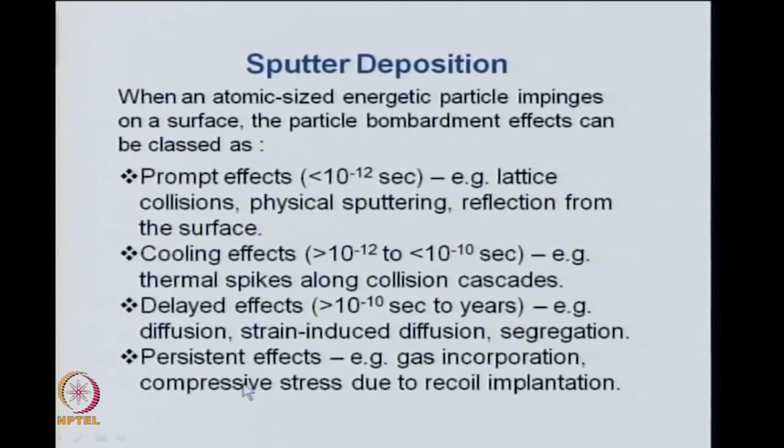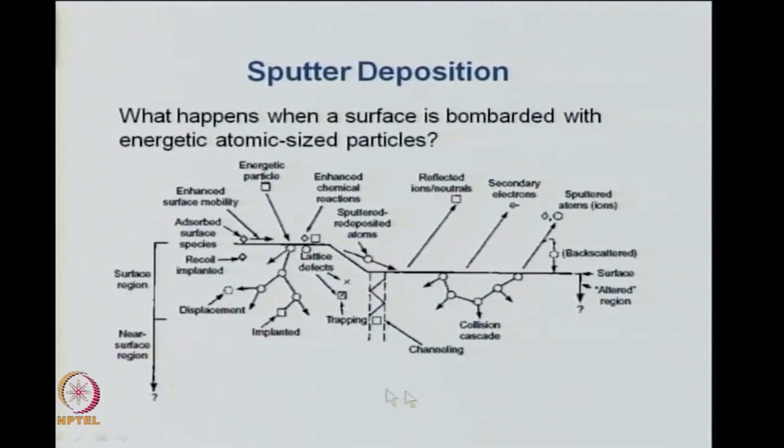And then there are what are called persistent effects, for example, gas incorporation or compressive stress due to recoil implantation. So, when you have implantation or recoil implantation, you can have these kinds of delayed effects or persistent effects in these sputter deposited films.